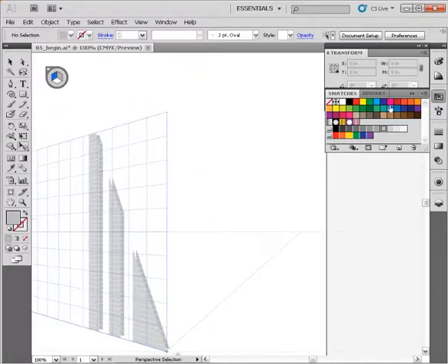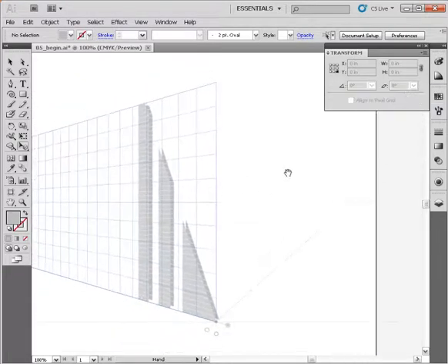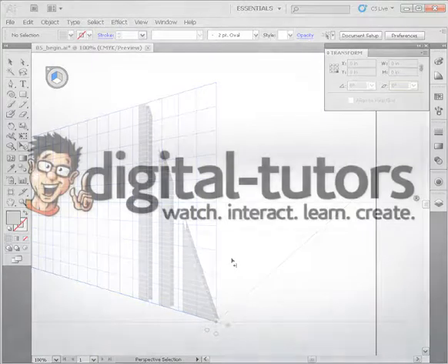All right, so hopefully you can see exactly how beneficial the transform panel can be, especially when you're looking to precisely move objects or even perspective grid planes. Now, in between lessons, go ahead and practice using the transform panel to move objects around your perspective grid planes. Also practice making copies of your planes and really get used to this sort of workflow, because we're only going to build on this from here on out. So in the next lesson, we'll pick up where we're leaving off here, and we'll learn how to automatically position our planes.